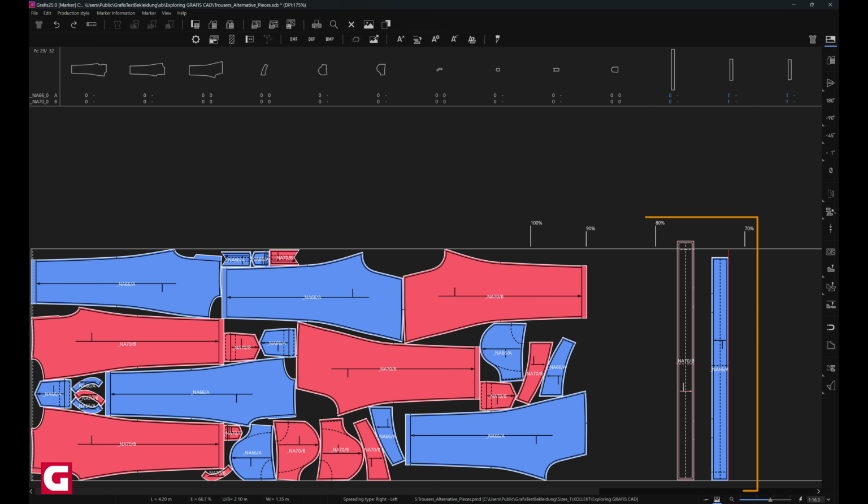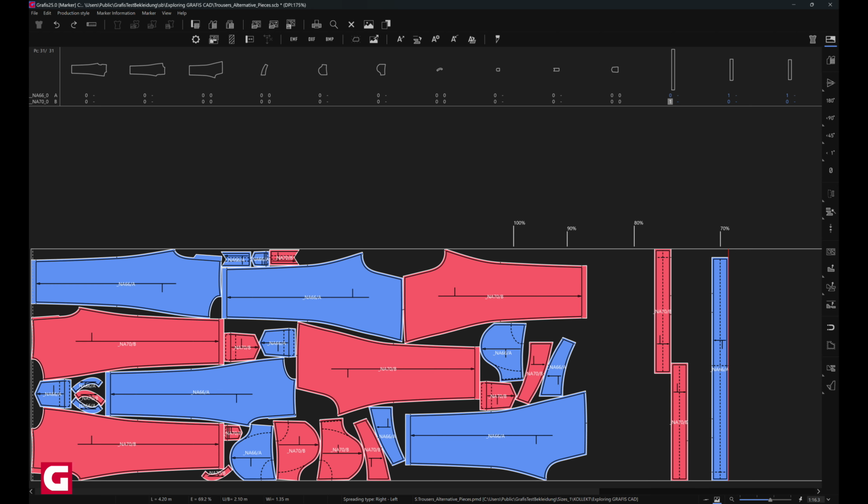With the Alternative Parts function, various groups of production parts can be defined where only one variant is laid out each. In this way, a continuous waistband could be automatically split into two parts, for instance, if the material width is insufficient for larger sizes. If the marker is created using the Autonester, the appropriate alternative group can be determined either by efficiency or by material width.